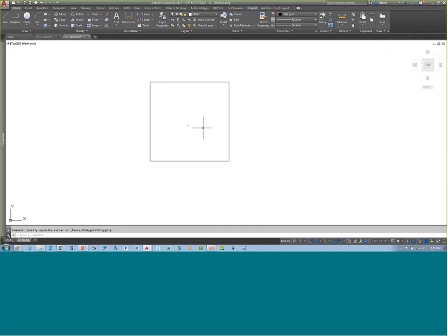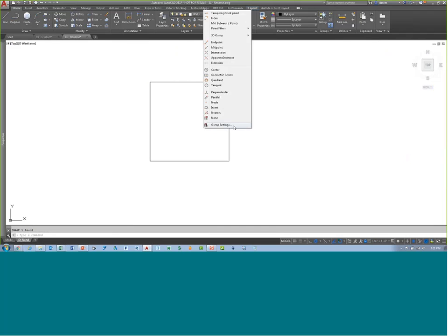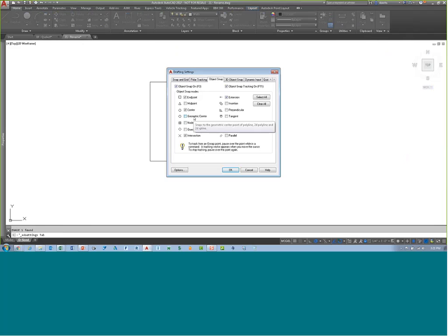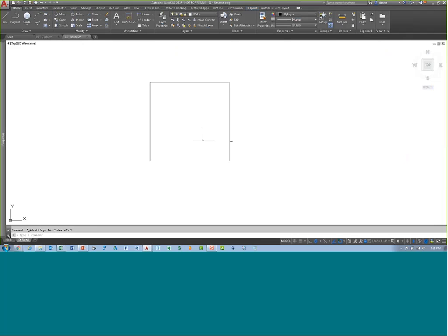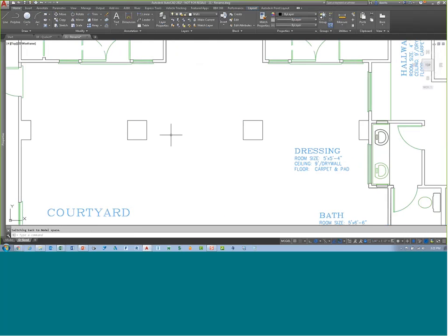Some people would prefer they have their object snaps turned on and say turn on geometric center. And so if I start the circle command, I can actually find the geometric center, assuming that this is allowable. That geometric center works better a lot of times when it's strange objects like this, surprisingly. So if I start the circle command, I can see that geometric center and draw that.